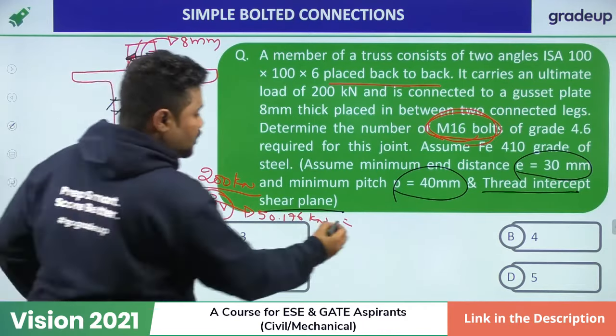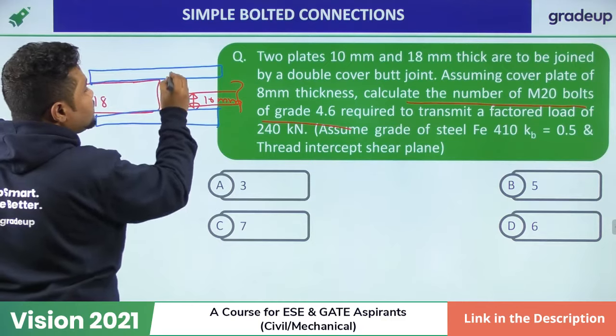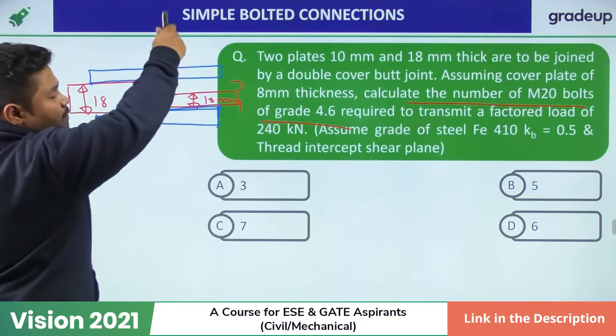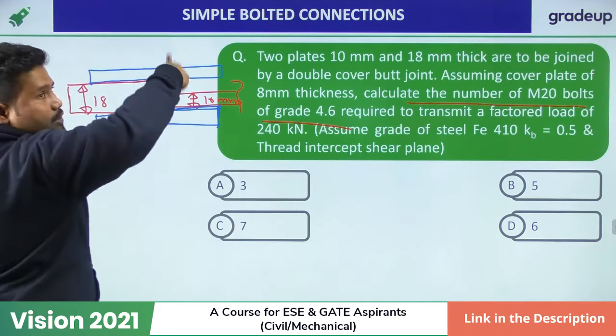Okay, so when two plates are kept side by side, this is how I can keep the cover plates. But you can see there is a gap between this cover plate and this main plate. So to avoid that in the bolting here, we generally keep some packing plates. So let me go for a packing plate with another color. Maybe this is the packing plate.